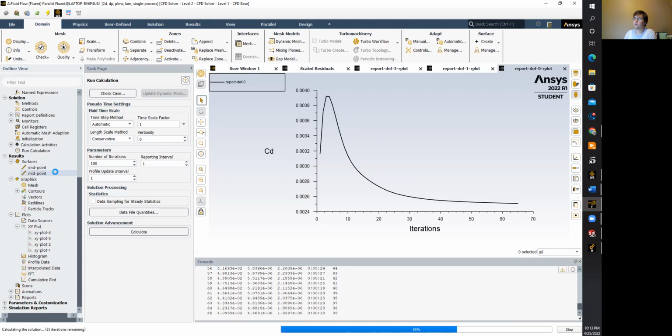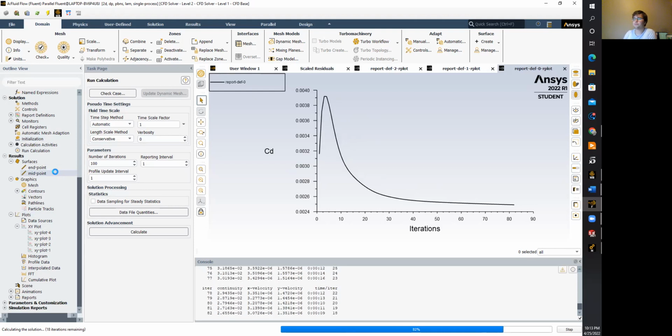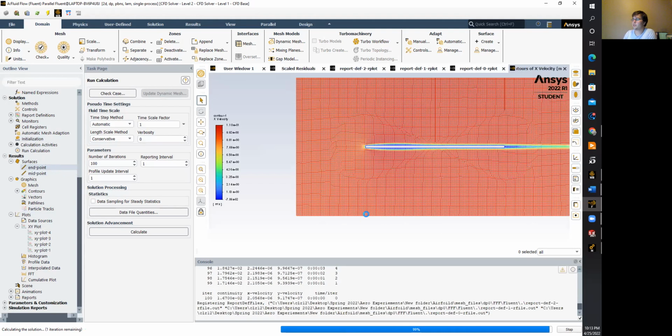What I ended up doing was converting 6 inches to meters, taking half of that for my midpoint, and then just leaving it for my endpoint. You do that for both of them, and I don't think it'll mess it up if I click. It won't let me. But essentially, that just creates a reference point for you to look at. Makes it a little bit easier.